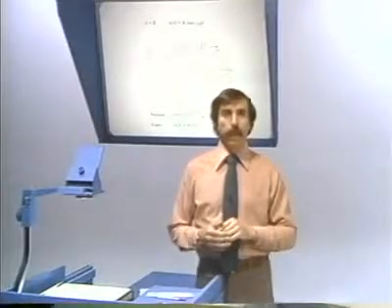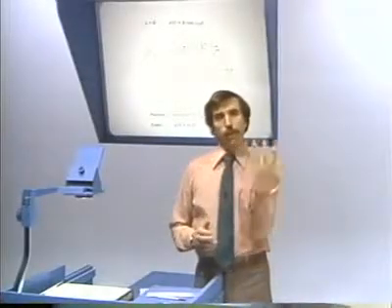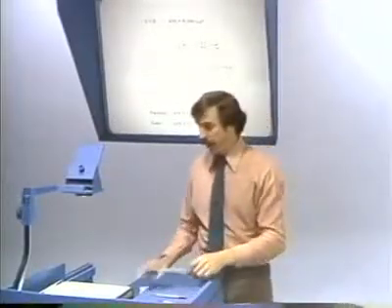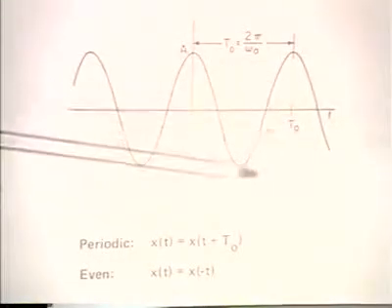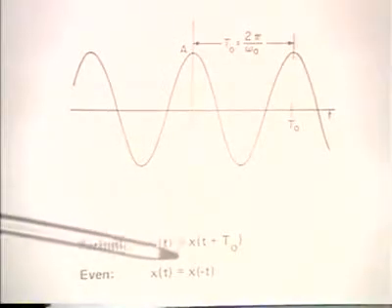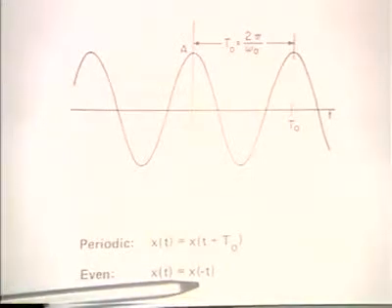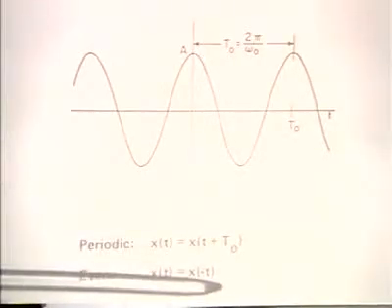to as even. And that's a property that we'll find it useful in general to refer to in relation to signals. A signal is said to be even if, when we reflect it about the origin, it looks exactly the same. So it's symmetric about the origin. And looking at this sinusoid, that in fact has that property, and mathematically the statement that it's even is equivalent to the statement that if we replace the time argument by its negative, the function itself doesn't change.